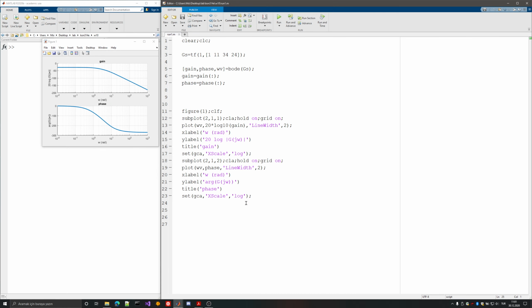Now, it is important to note that if you're talking about stability and if we're in the frequency domain, then what we will do is get the closed loop transfer function and just plug in s equals j omega. But the important part here is to use basically the open loop Bode plot. Since I didn't design any controller, I don't have exactly the transfer function that is usable for a Bode plot. I'm not able to generate the Bode plot. I need the value of the p-type controller.